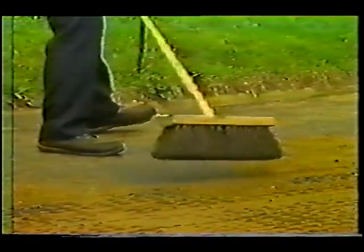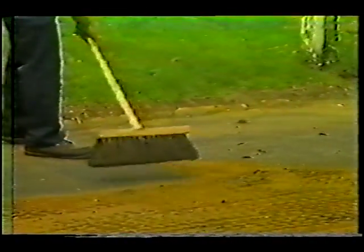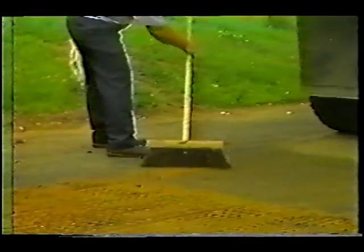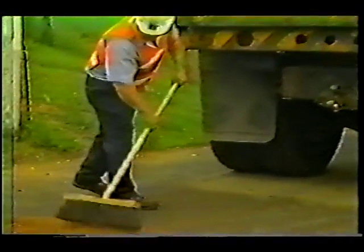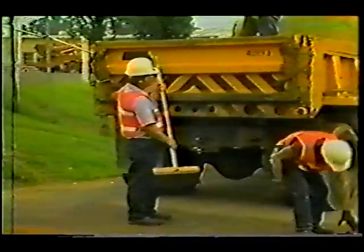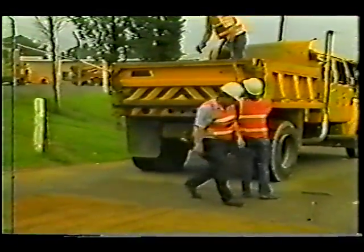Step 7. Clean the worksite. All unused material must be loaded on the truck. Do not leave any unused material at the worksite. Also, the tools used to make the repair must be cleaned at the end of the day and loaded back on the truck. Loose aggregate should be swept up and properly disposed of away from the road and drainage ditches. Check for anything left behind and be sure it gets loaded on the truck.